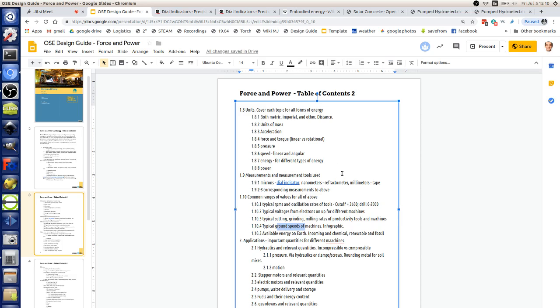But basically, in milling, depending on the speed that you have, that's a combination of speed and distance with which you're going through material. You will be able to calculate how much force is required to do that based on how big chunks you're taking off the material. That's a very basic concept. Obviously, if you're going slow, then a drill bit or a milling bit will take larger chunks. But if you increase the speed of that bit, it will take smaller chunks, and you will be able to use less force to do that machining.